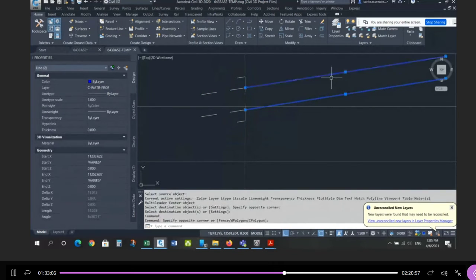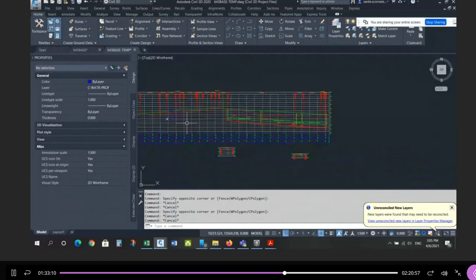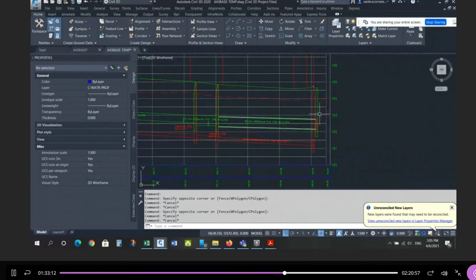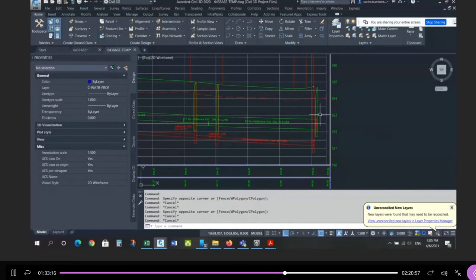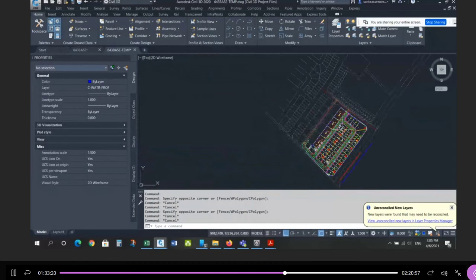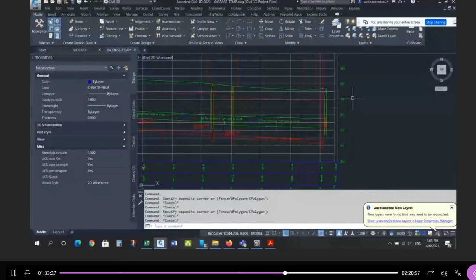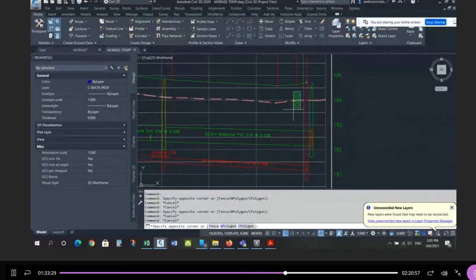And there's your proposed pipe connecting to it. So you need to show over here. Everything else from there all the way to the end of street B is proposed water main. This is street A. So there's going to be a valve chamber here. And it's probably going to be, let's take a look. It's going to be storm, and water on the other side. So you're going to have your storm, your sand, and your water main is going to end somewhere over here.